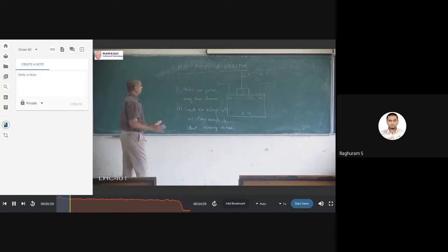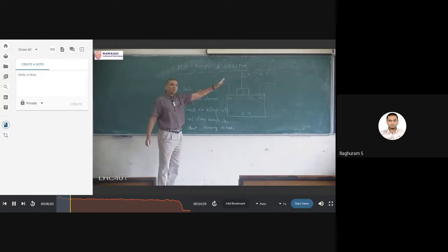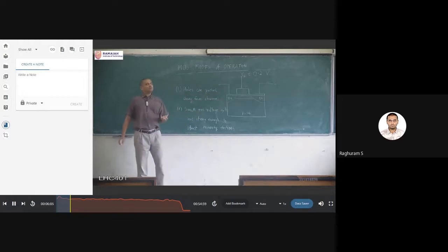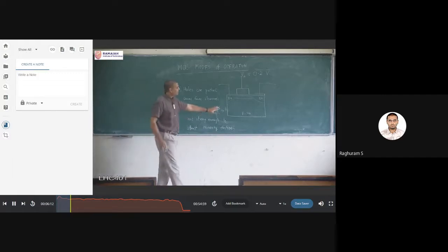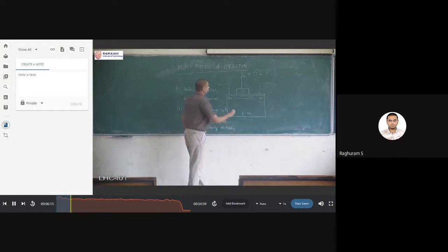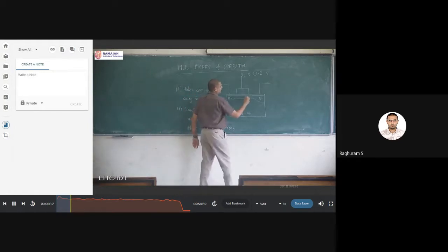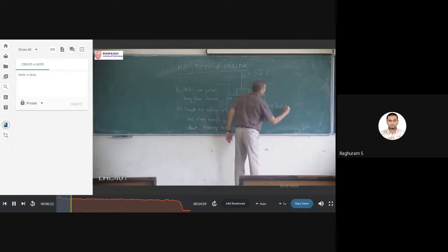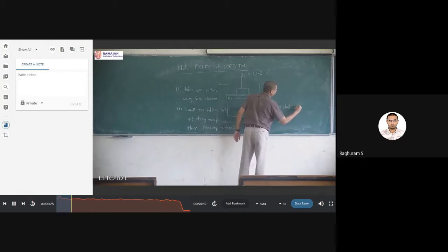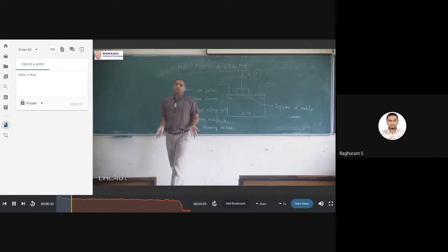So this very small positive voltage is not strong enough to attract those minority electrons which are spread through the substrate. That is, in this p substrate there will be electrons all over. So in this region, that is the channel region, holes are also gone, electrons are also not there.